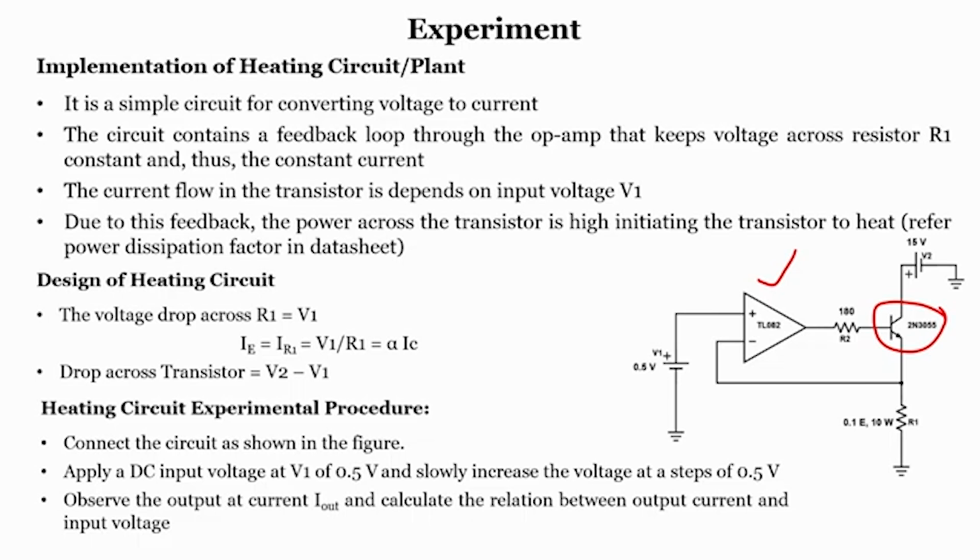Just to realize, if you recall, we are taking a transistor in our circuit, and here we have a resistance, and we are saying the resistance value is 0.1 ohm, and the wattage is very much important. Here it is connected to supply VCC. As you know, this is an NPN transistor, and this is 2N3055. Why have I considered the 2N3055? Because the 2N3055 is a power transistor.